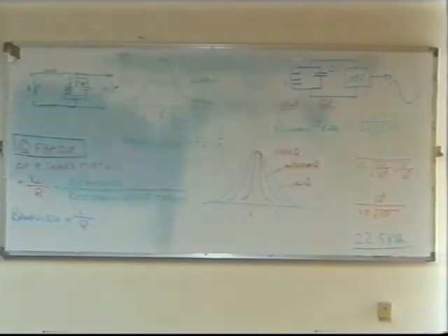If you take your formula F0 over Q, you see, the problem is this. That's at resonance, so you get one frequency. That's true, and it will give you an approximate answer, but it cannot give you the exact answer, because as soon as you go off resonance, you change that formula a little. It's only a small amount, but it does change, because XC changes, XL changes, and XL is no longer the same as at resonance. I wasn't going to give the formula F0 over Q because of that.